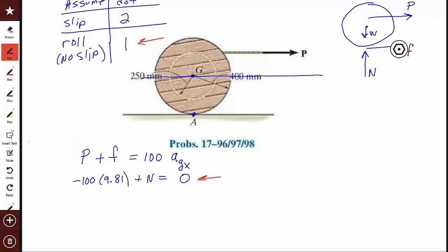So whenever in doubt, sum around the center of mass. Your equations will be okay. So I'm going to sum around the center of mass. Counterclockwise is positive, so that I have a right-hand coordinate system, right? So I is this way, J is this way, and the K would have to come out or be counterclockwise. So that's positive is counterclockwise. Okay, so here we go.